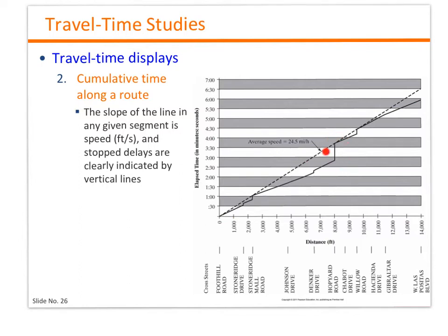So this again, the length, this abrupt increase, or this increase here, shows you the amount of delay, because now the car stuck at that location for that amount of time, and now once the car starts to move again, it catches up with the dashed line. That means again it catches up with the average speed one more time, and again you have some delay. Once the car starts to move again, it goes back to the dashed line, and so on and so forth. So this is again another way to represent the travel time and the associated amount of delay at every checkpoint.